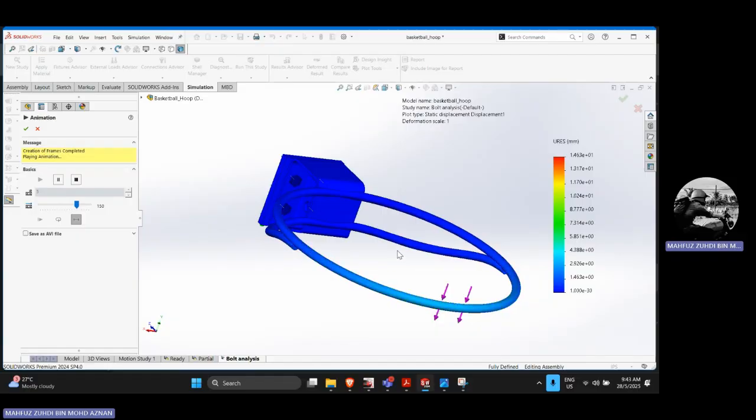Also, the main part is the material optimization. Maybe we can use a better material, which is stronger and more durable. Alloy steel is suitable, but if weight is a concern, we can consider high strength aluminum with similar yield strength and reduced mass.